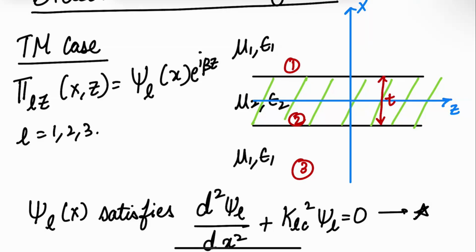Similarly, for a PCB, you have a dielectric on top and then air, and they can have substrate modes. And we saw that essentially substrate modes are nothing but this TM0 TE0 case. And interestingly, they can propagate even down to very low frequencies, down to DC. The consequence of that is that substrate modes in a PCB can exist even down to DC. And that's why it's important to understand how they get excited and how they propagate. And this is the theory behind that.